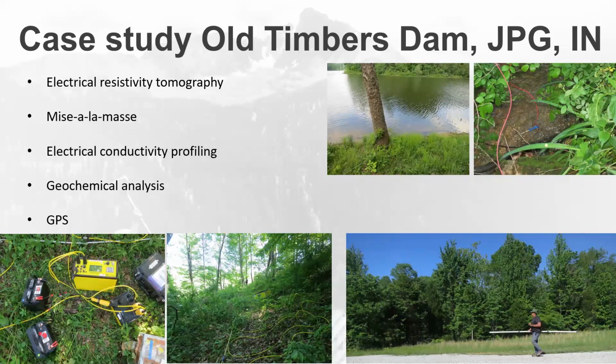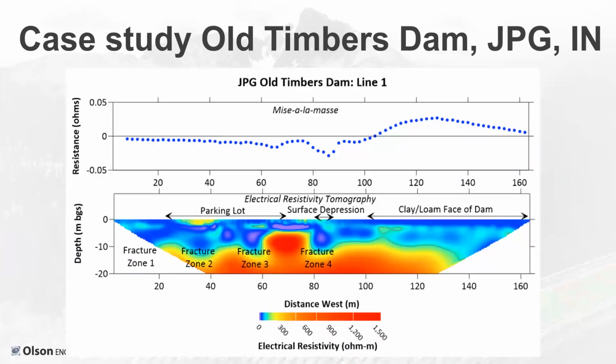And on the downstream, left side downstream, it actually went out into the woods there, and that part was not mowed and maintained. And that was an unusual field experience where I managed to cut all of our tape measures with machetes in the course of 2 hours. It was a little frustrating. Then on the right side is me carrying the Geonics EM31 to do conductivity measurements.